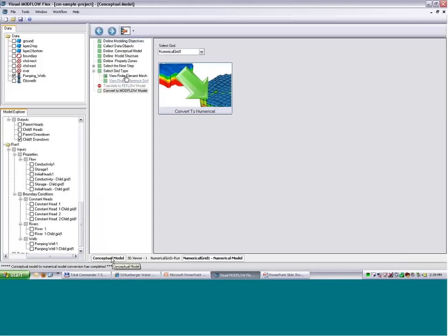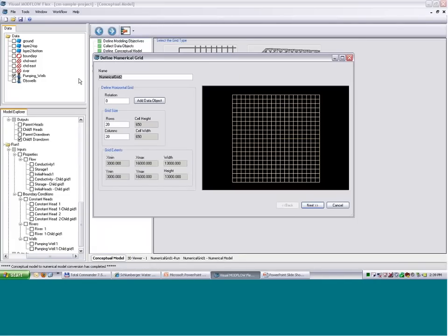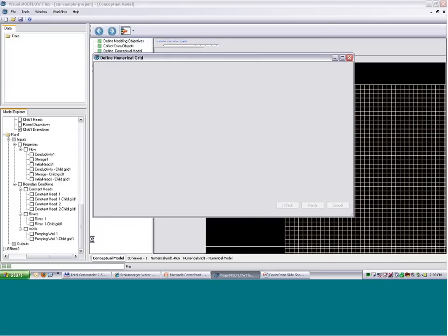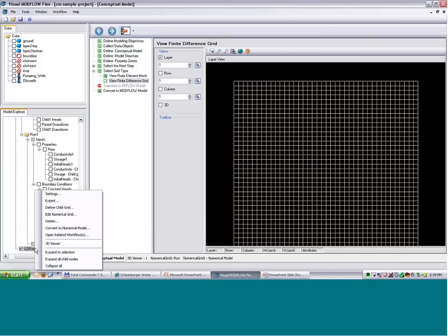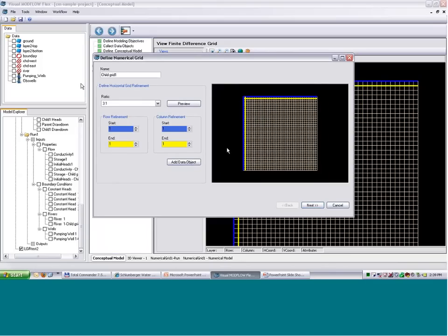So if I go back to the grid generation step, I can create another LGR run with, for example, a larger parent grid if you wish. You can then add a new child grid onto that region with whatever refinement ratio you want.